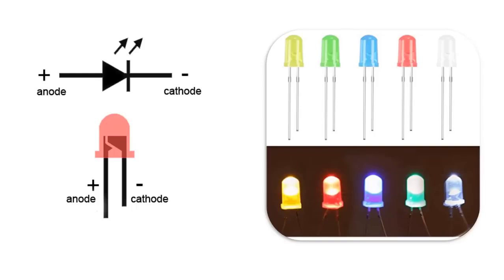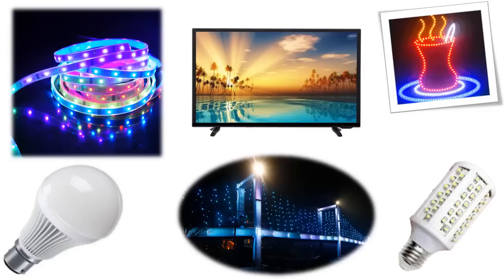Like all diodes, the LED is polarized and electricity is only intended to pass through in one direction. LEDs will show up in a schematic as a diode symbol with lightning bolts coming off of it, to indicate that it is a glowing diode. There are typically 2 indicators to let you know what direction electricity will pass through an LED.